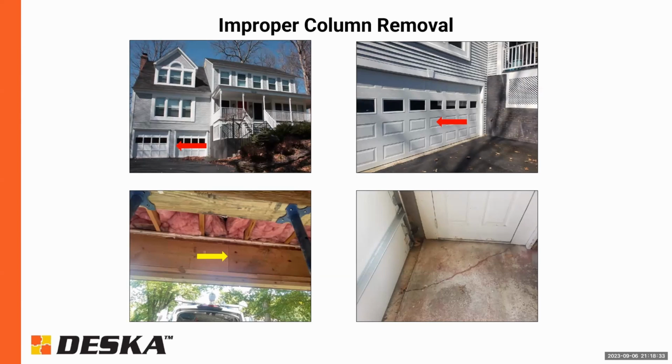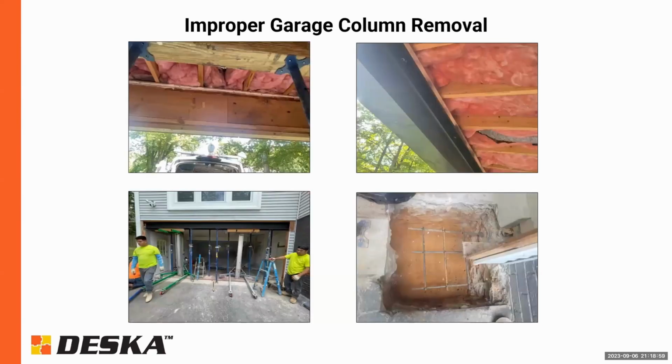It's a major no-no. And then also because you remove that center support, you now have increased the loads at each of the corners as well. And then they're having settlement issues at the corners because the footing there was not designed to support those increased loads. So in this particular case, this 2-ply 2x12 was replaced with this.